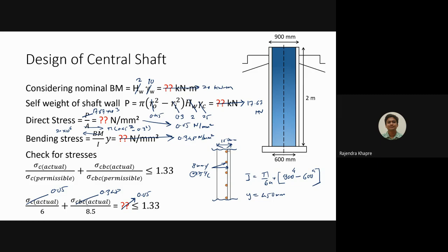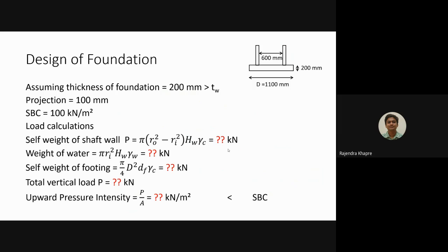So are there any queries? Fine. So we will quickly go through the design of foundation. Foundation is pretty simple. It's a simple circular foundation. The basic rule of the foundation is that whatever is the thickness of the wall, we have to provide the thickness of the foundation greater than that.